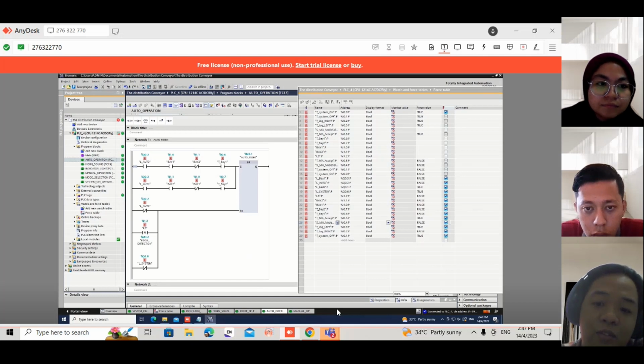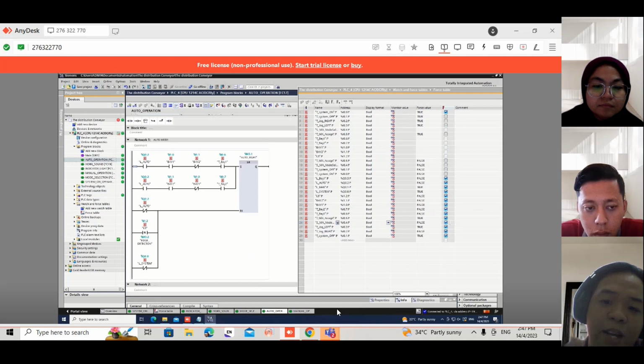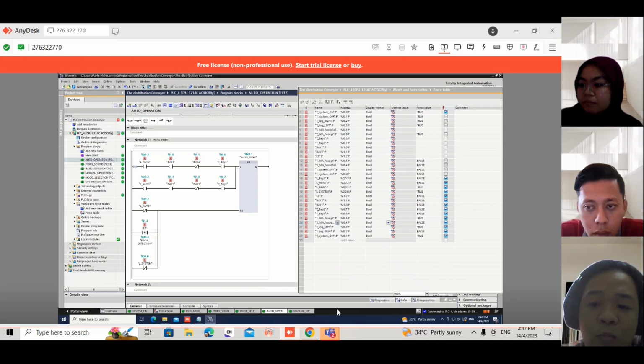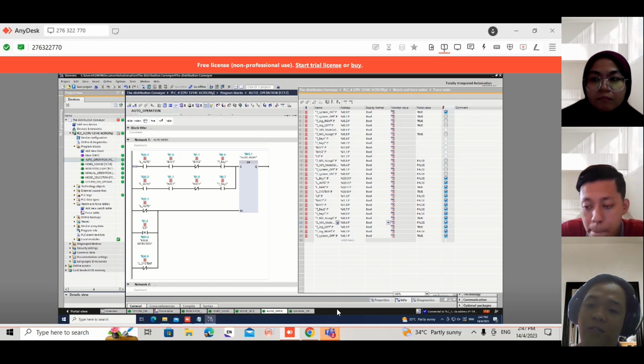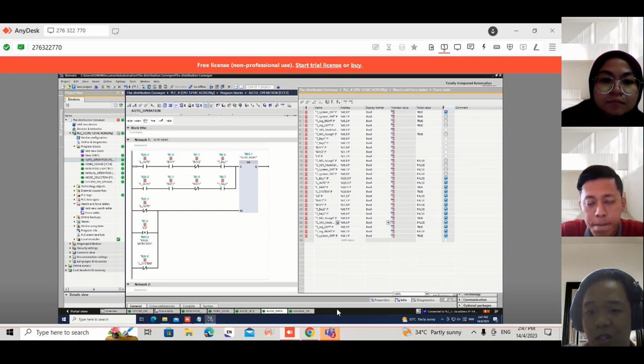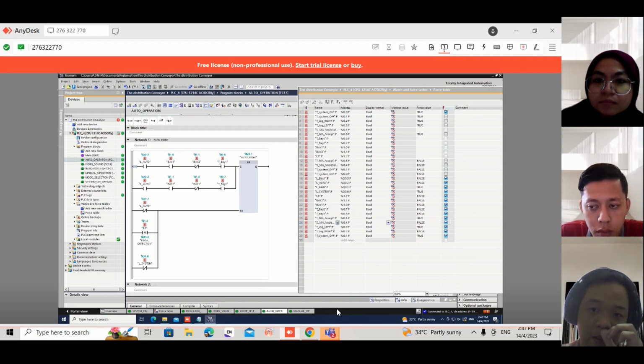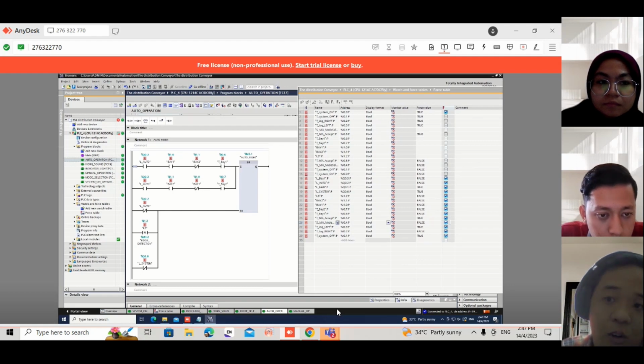And in exercise 5, the requirement is to stop the conveyor motor as soon as the part has passed through the light barrier. This indicates a change in the stopping condition of the conveyor motor in auto mode. Previously, the conveyor motor was stopped when the part reached the final check or light barrier, but now it needs to be stopped as soon as the part has passed through the light barrier. Okay, for exercise 4,